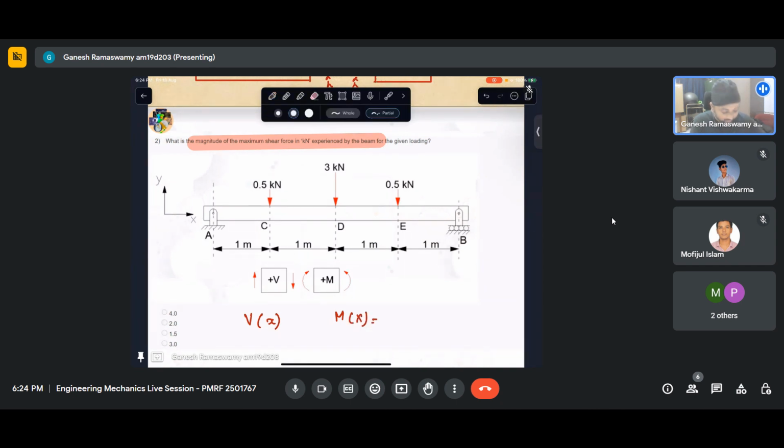How are these useful? Once we plot a shear force diagram and bending moment diagram for a beam, at once I have a representation of how the variation is and what the extrema are, that is, positive and negative bending moments or positive and negative shear forces. And when we design beams, we will essentially be considering only the maximum of those values.